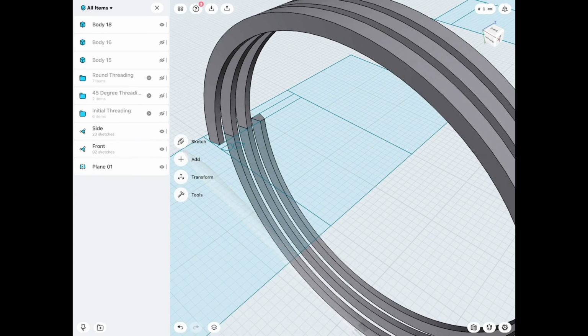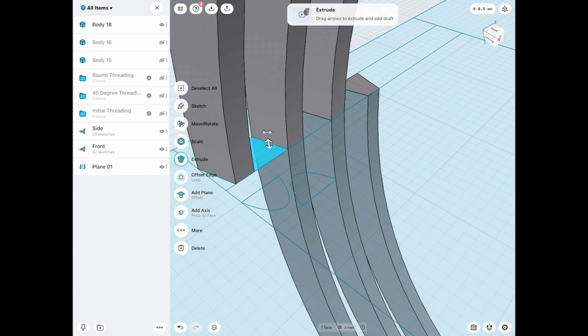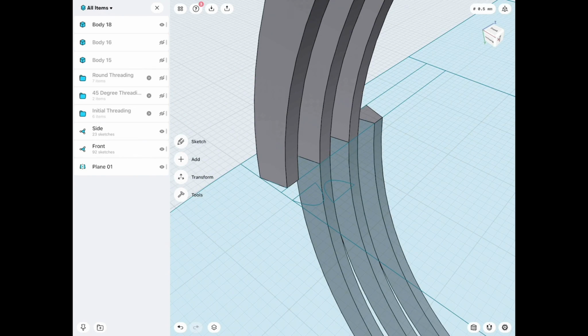And then all those, to make it into one, I can join together. Now if I would build the piece that is in between, the threading would be perfectly next to each other. That's not good, because the 3D printing will have some deformities plus issues on the surface, so we want to add a tolerance, a little bit of spiel in between. This is actually very easy.